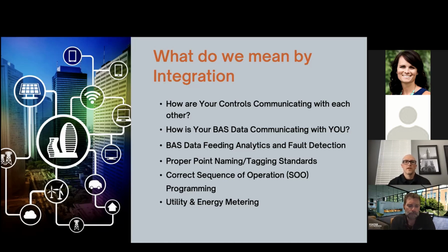controllers. And that really, Mike, to that point in integration, in terms of if you have things kind of teed up for you as an integrator or as an engineer coming into a building to start pulling data out, that could really mean the difference between starting to see data and trends into your analytics and fault detection program within minutes or within weeks and months, because that could really be a giant bottleneck. Even if somebody says they can get BACnet out of your system, it really does take some time and effort and coordination between yourself, the building owner, their proprietary systems that are there and things like that. So it could really be a bottleneck.